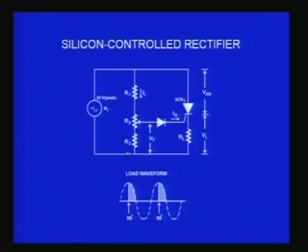For example, I have shown you this circuit here. I have put the gate current also from the same AC. The AC is connected to the anode and the cathode with the load here, and I have also connected a potential divider and derived from this, and I put a diode, therefore it is rectified. So I have a DC current here flowing, which is also in the form of a sinusoid now. And now when I increase this position, you find it can trigger at, say for example, 90 degrees. In this sinusoid this corresponds to 0 volts, this corresponds to 90, 180, 270 and 360. So that is corresponding to one cycle.